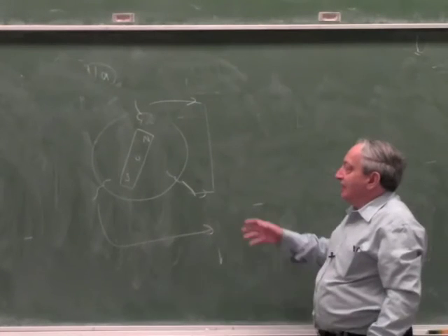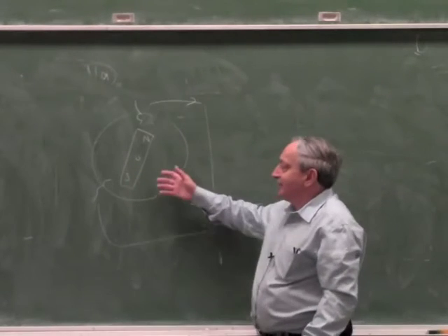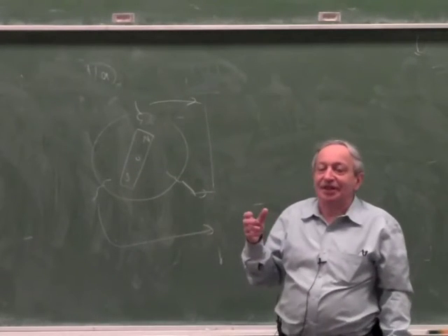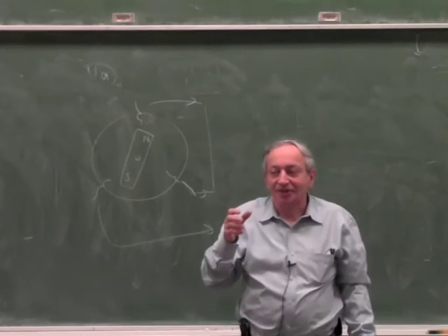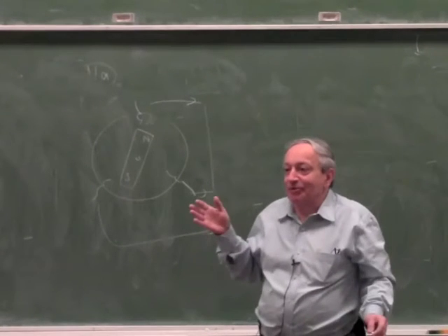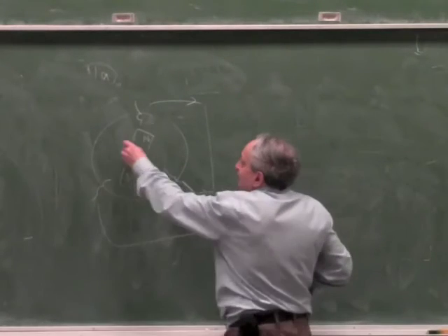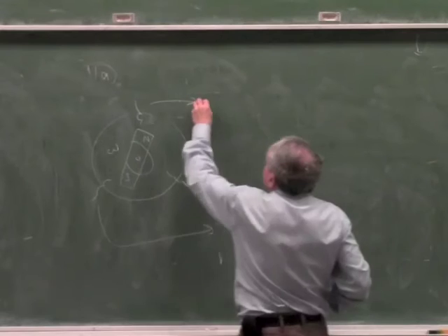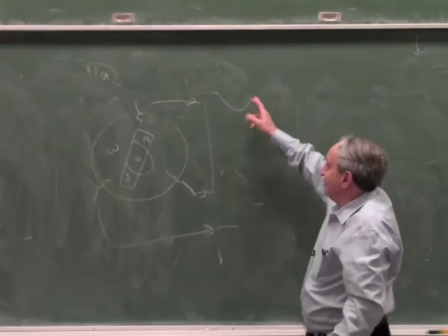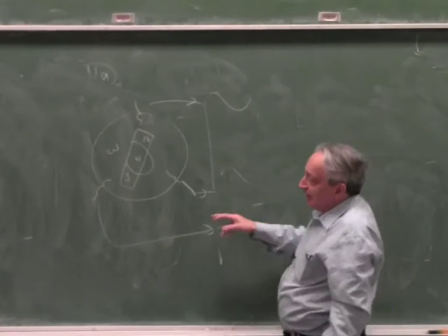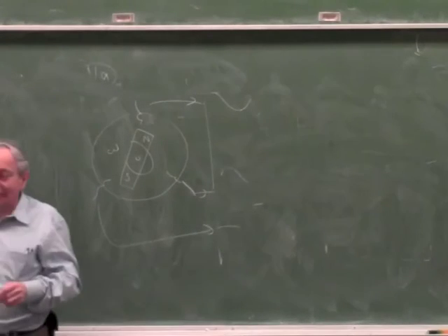Here it's even easier than a motor, because a motor had problems starting with a load. It had low starting torque, but as a generator you don't care about torque, you are driving it. So if you drive it at a frequency omega, it will generate 3 sine waves, and you get a 3-phase generator, and you can rectify this and feed the power back to the battery.